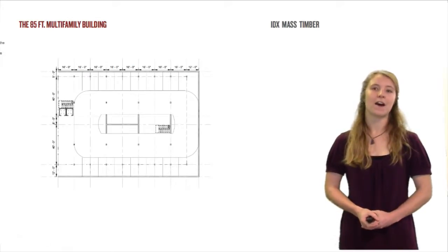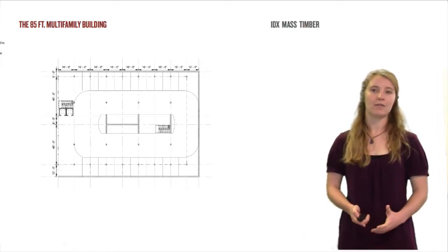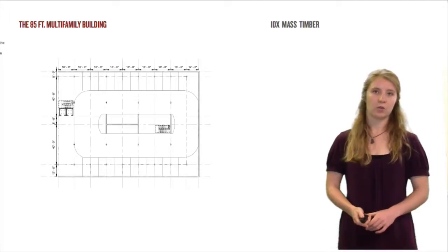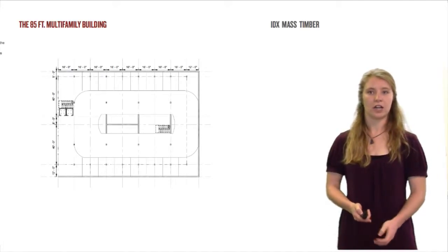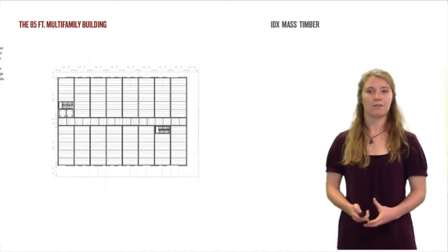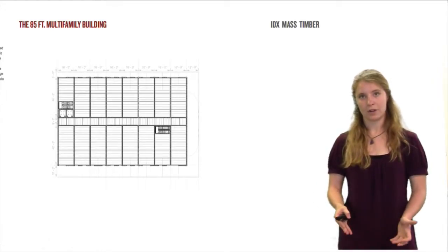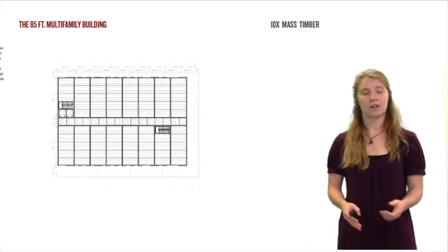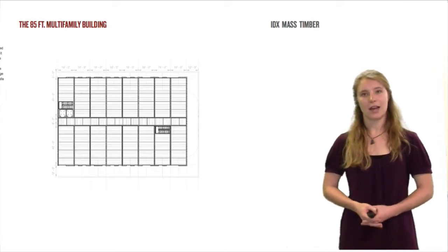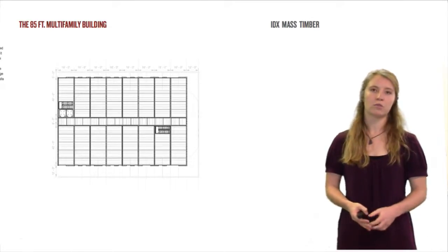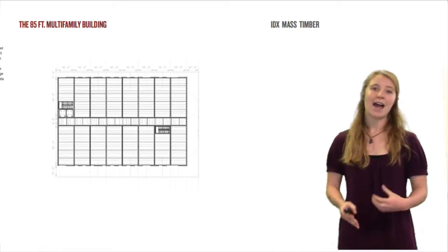Finally, we have that 85-foot multifamily office, and again, we see the parking garage with your shear walls, which in this case are also concrete, your stairs and your elevator shafts, and overlaying that floor plan, we can again see that the parking garage is going to be bigger than the developed floor plan, and those stairs and elevator shafts continue up.